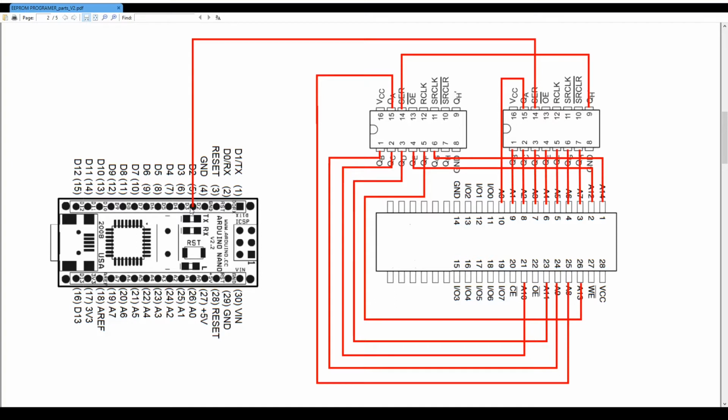And the way this works is it receives the serial address from digital pin 2 of the Arduino into the serial input of the first shift register, and by each clock pulse, that we'll see in a moment, it stores the bit in one register, and by the next clock pulse it shifts this bit to the next register and stores the one that came from the serial input in the first one. And so it shifts all the bits in the registers it has inside.